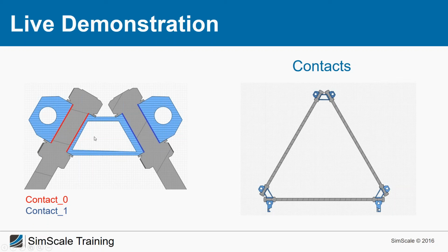And therefore we need a third contact which is connecting the lower surfaces of the nuts to the surface of this connector. And this, guys, is a very, very important point, maybe the most important point. Defining the contacts needs a lot of experience sometimes, because it's not like a black or white solution. It's more like an approach you have to find.